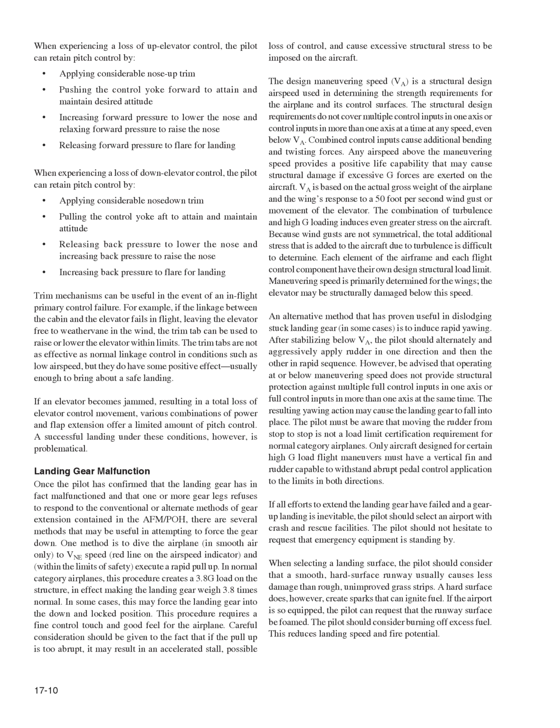This procedure requires a fine control touch and good feel for the airplane. Careful consideration should be given to the fact that if the pull-up is too abrupt, it may result in an accelerated stall, possible loss of control, and cause excessive structural stress to be imposed on the aircraft.